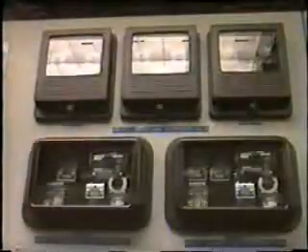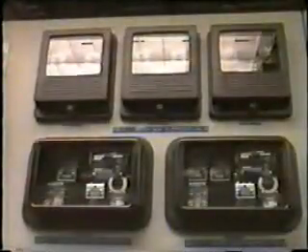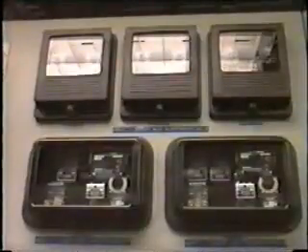Okay, based on the discussion of bus protection, I think it becomes quite clear that this type of protection does present a few special problems. First, because of its strategic position in the power system, any operation of bus protection relays will clear many circuits and probably cause a major system upset. For this reason, we do not want the bus protection scheme to operate unless there really is a fault on the bus. However, when there is a fault on the bus, it is important that the protection relays operate and clear the bus as soon as possible, preferably at high speed.